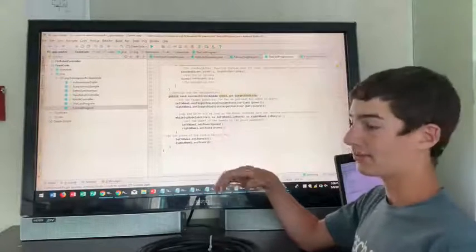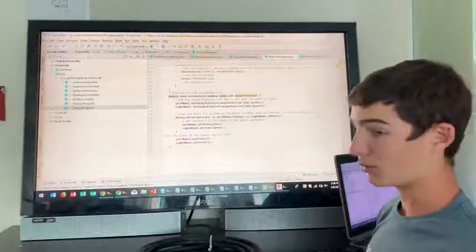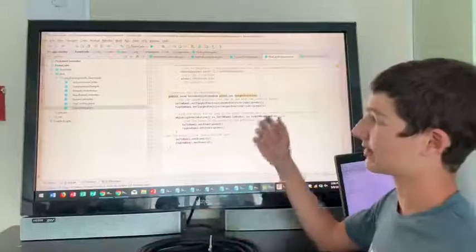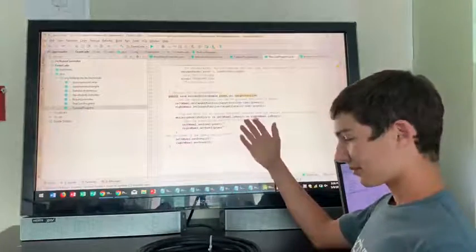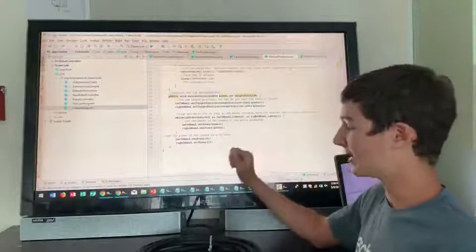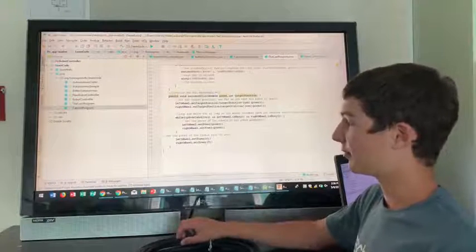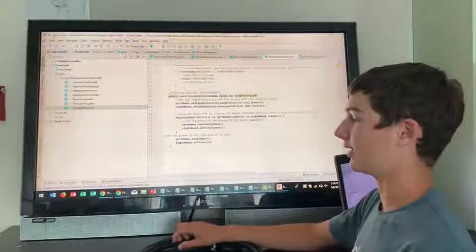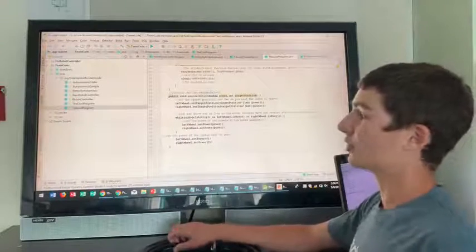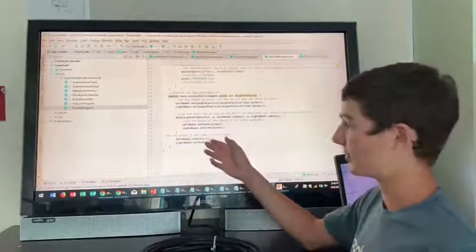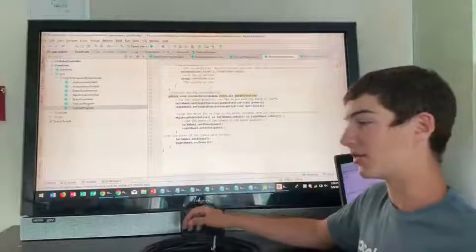It's divided into multiple measurement units called clicks or ticks, and basically there are not 360 of them in one rotation, so you need to be careful about that. There are a different amount of ticks per motor. So like a normal 60 motor or a 20 motor or 40 motor, they all have different amounts of those measurements. So you have to be aware of what motor you're working with.